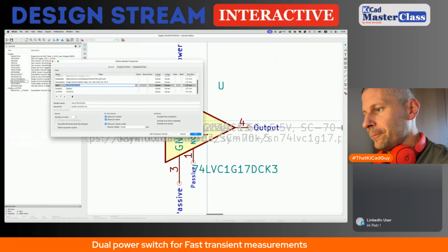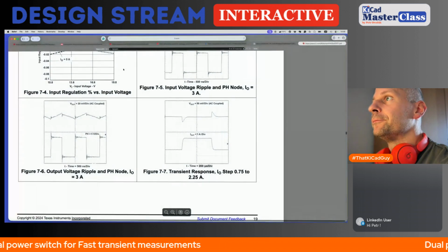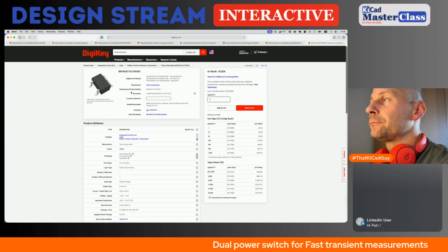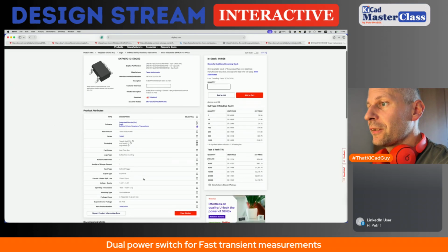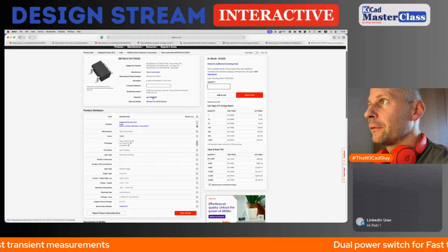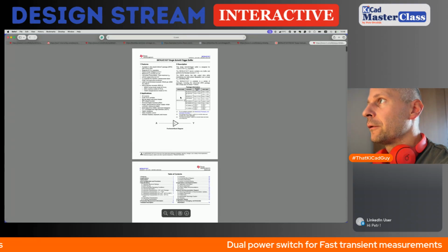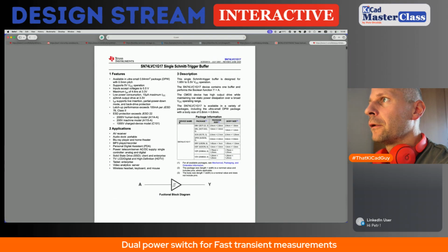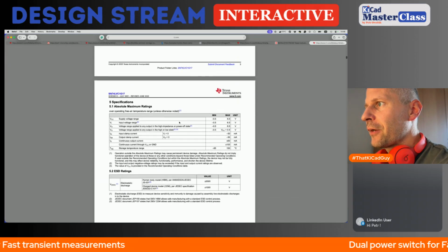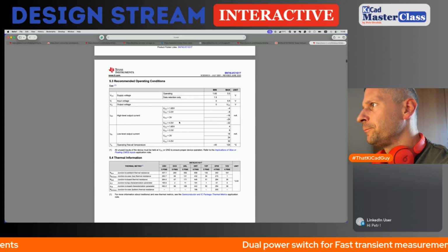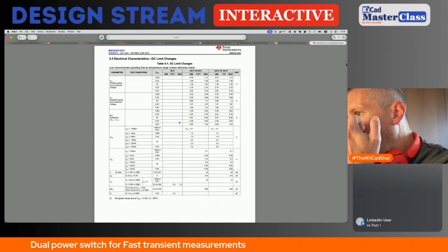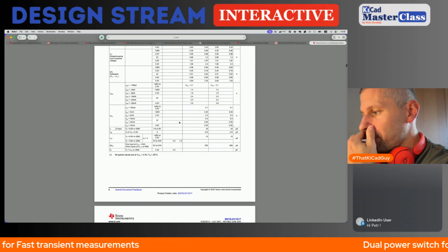So let's check the price availability, because this Schmitt trigger is definitely an alternative to the digital output optocoupler, because we need another isolation, and driving capability of this Schmitt trigger is not so important because we drive only the gate driver.